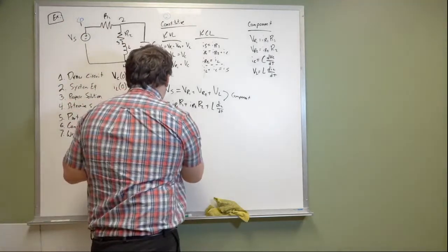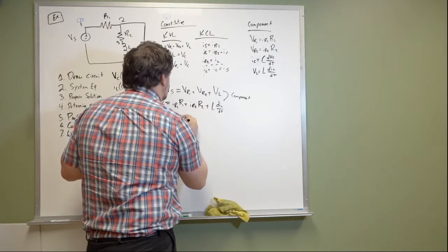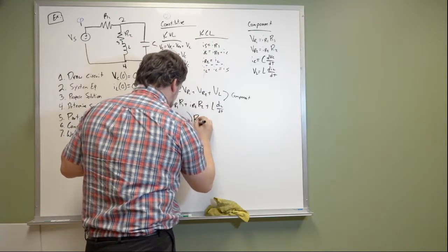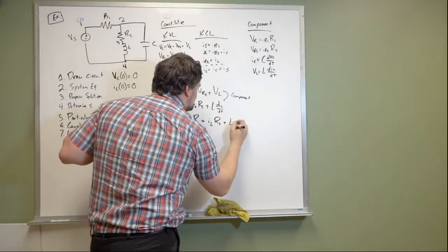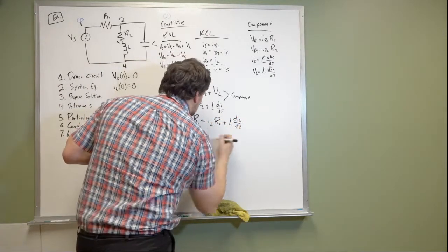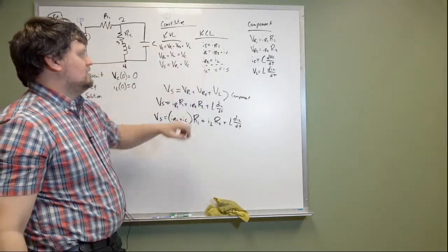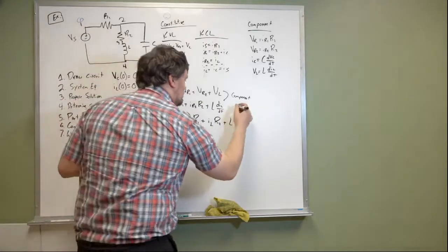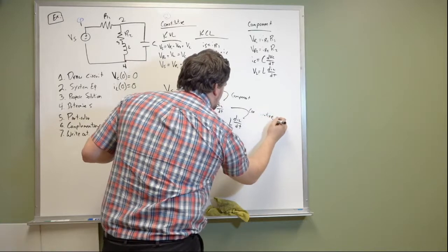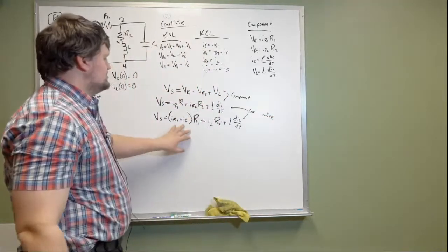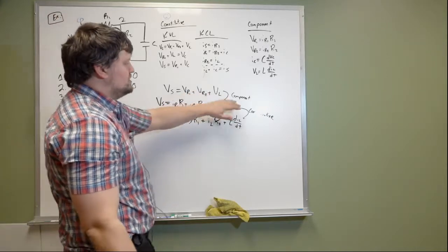So here, VS is equal to, and I will put in, IR2 plus IC times R1 plus IL times R2 plus L dIL/dt. Okay, now we know IR2 is equal to IL. That's a nice piece. So I should say this one is constitutive. That is an easy transition. This piece here that we don't have is IC. So here we've done component, constitutive.